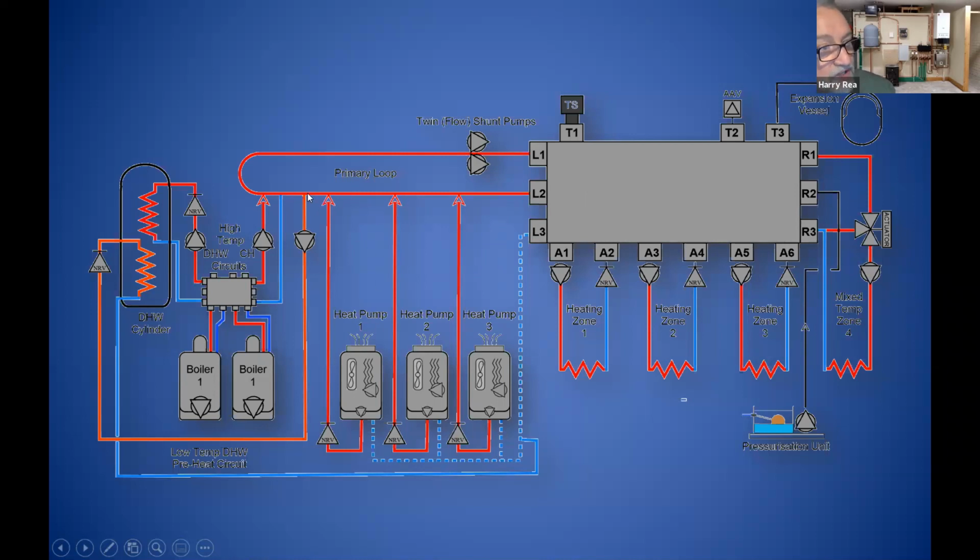Then we take the hottest water from the heat pumps, let's say 45-degree water, and we go down with a pump and we feed a preheating coil in the hotel's hot water system. So we got low temperature preheating on the hot water. Then the water comes back from the coil, it's put through the heat pumps again, and so that can carry on. But the main shunt takes the hot water, the heat pump water, across to this point.